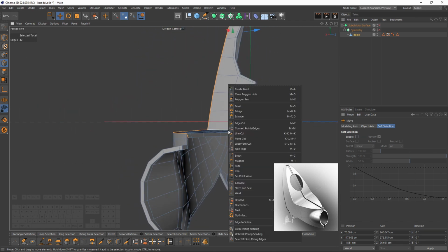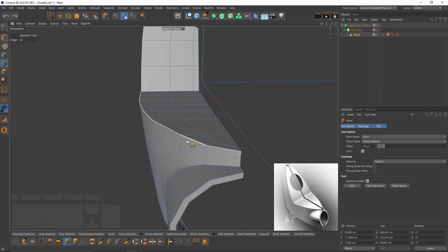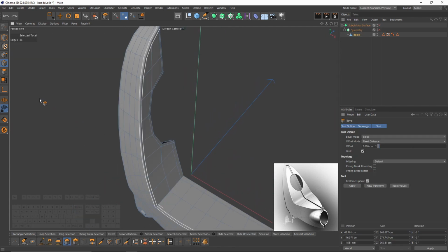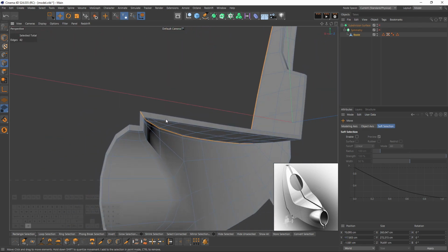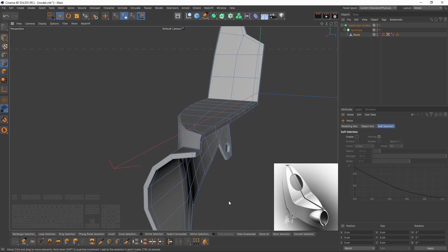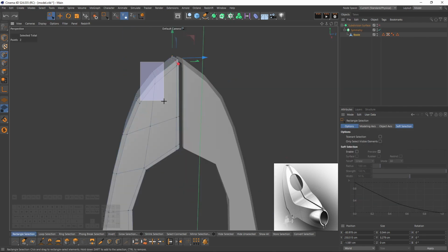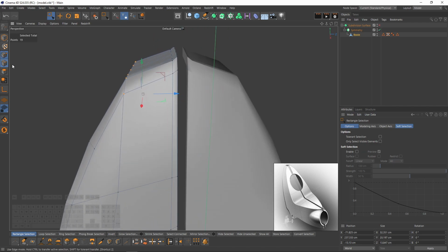I think we can use bevel for these. Select bevel. Instead of chamfer, solid will be better though. Let's make it solid. This might be too much though. So I can select the center edges by double clicking on them and solve them. Okay, that feels better. Here looks too sharp, so I'm gonna hide these. Then these ones.